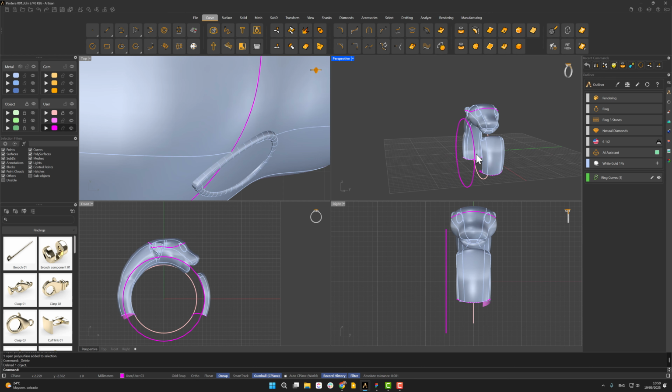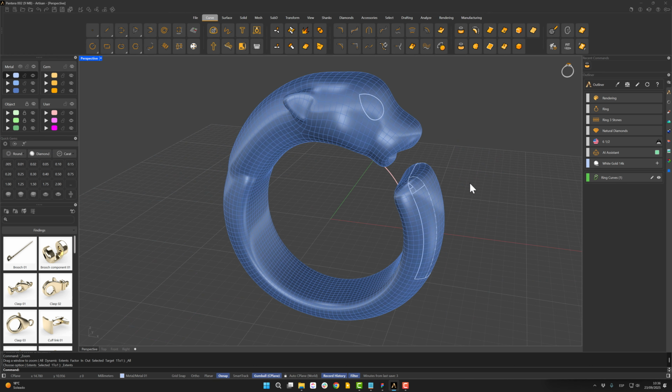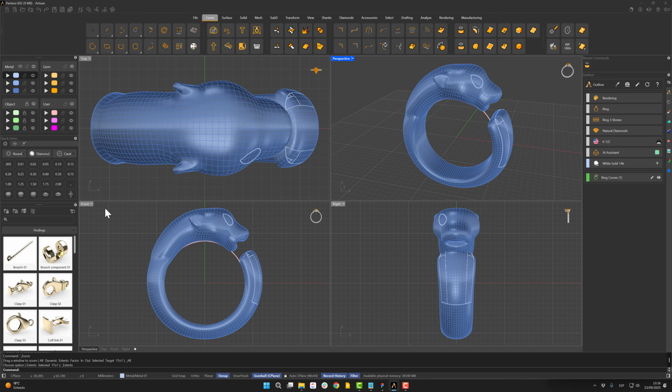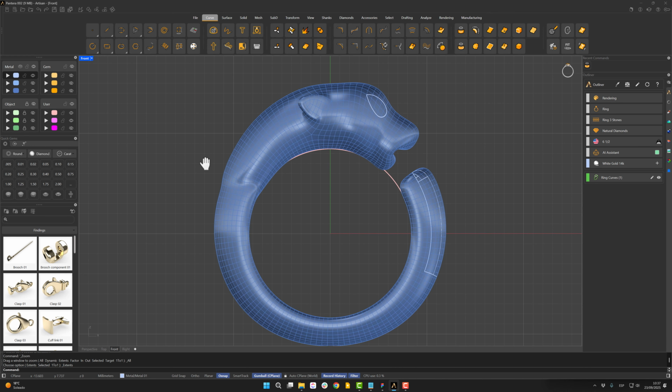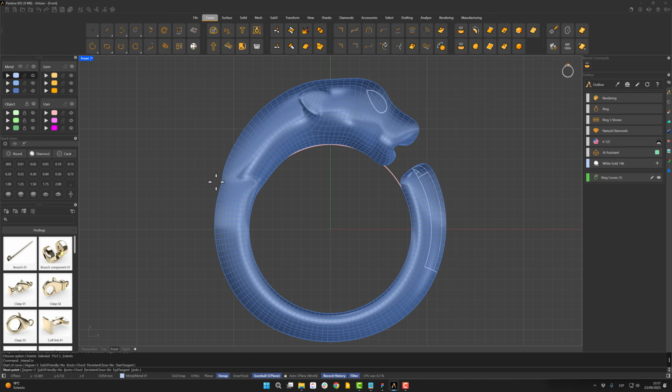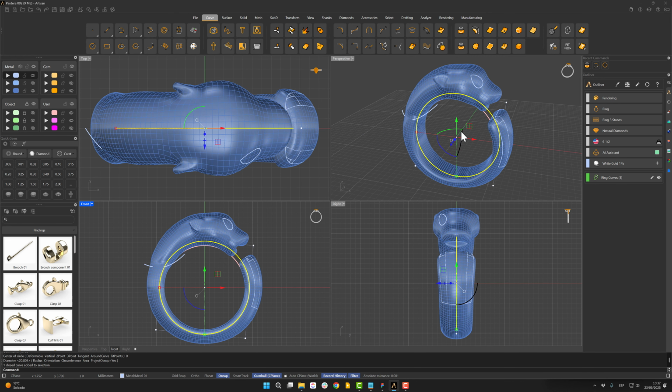For the second area, we will show the copied Sub-D we still have. It is important to also show the offset curve of the gem. From here, we will create some reference curves. From the front view, we will use the Curve command to create a curve in the union area of the shank. Then create a circle that comes out a little from the inside of the model to later cut the inner part where we will not place gems.